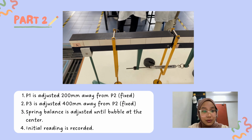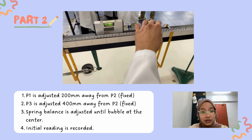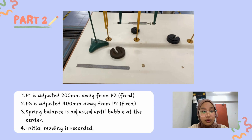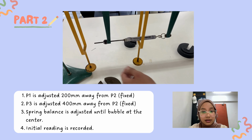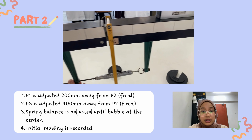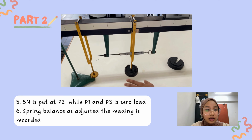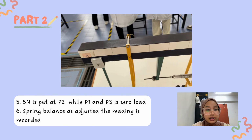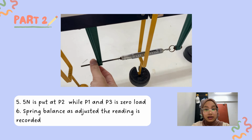For part 2, P1 is adjusted 200 millimeter away from P2, and then P3 is adjusted 400 millimeter away from P2. After that, we adjust the spring balance until the bubble goes to the center, and next we read the initial reading and record it in the table. After that, we put 5 Newton at P2, and for P1 and P3 there is zero load. Then we adjust the spring balance and record the data in the table.